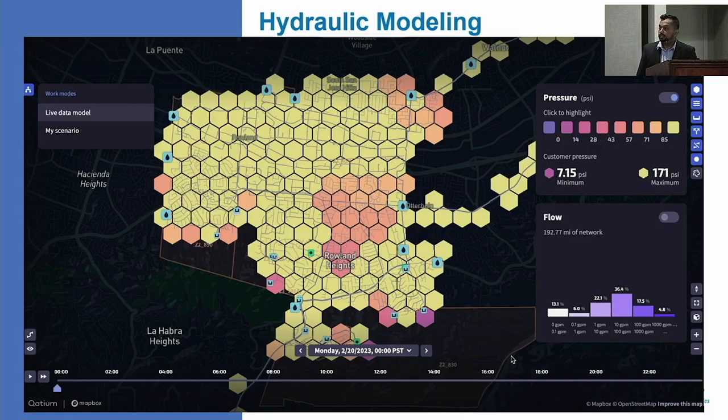The benefit of using this live hydraulic model is, let's say you have a SCADA system in place, but there is no current integration where you can pull in all the monitoring data. We do not check any of the control tags, but we check the monitoring tags. We have a backend which pulls all this SCADA data into the hydraulic model. We have also developed a program where we integrate all the AMI data from the meters and push it into the hydraulic model. Basically, the hydraulic model is now aware of the rules for the pumps and the tanks and what's going on in the system.